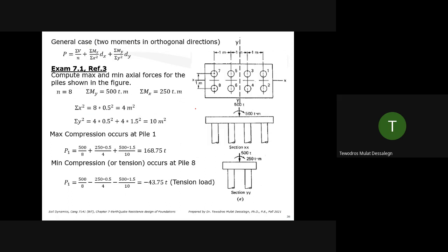All we do is, for the pseudostatic approach, the same equations will be applied. Except now the difference is the inertial forces are contributing in addition to the static eccentric loads. So that response spectrum we did in chapter 4, the corresponding peak ground acceleration or the corresponding spectral acceleration, depending on what structure you have, then you get the acceleration.